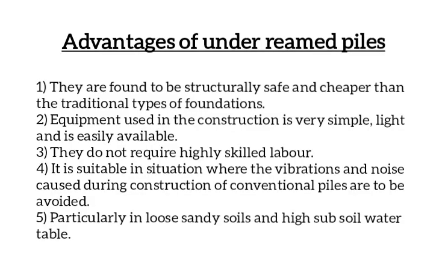It is observed that structures built on expansive soils often develop severe cracks due to differential movement of ground caused by alternate sinkage and swelling with seasonal variation. Apart from increased bearing, the enlarged pile base provides anchorage to the structure at a depth where effect of volumetric changes of soil due to seasonal variation is negligible.